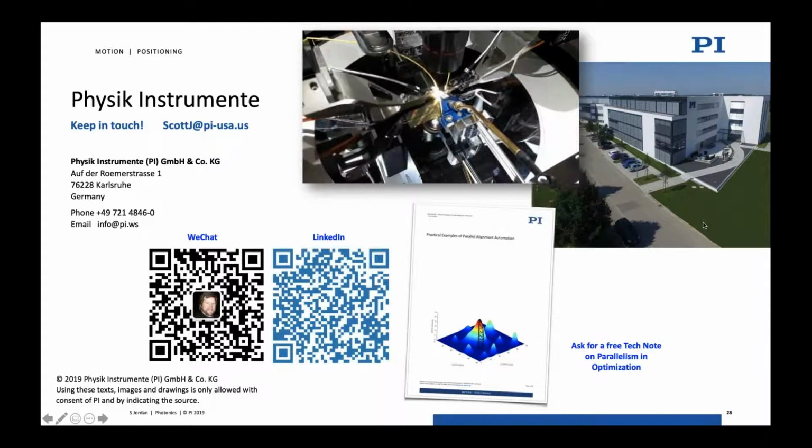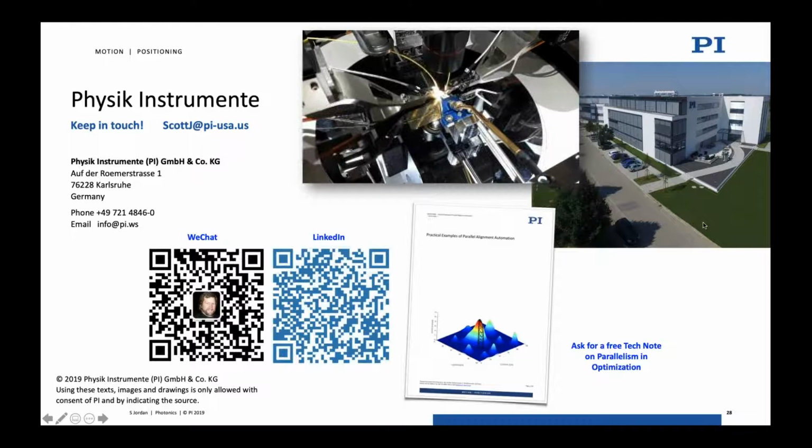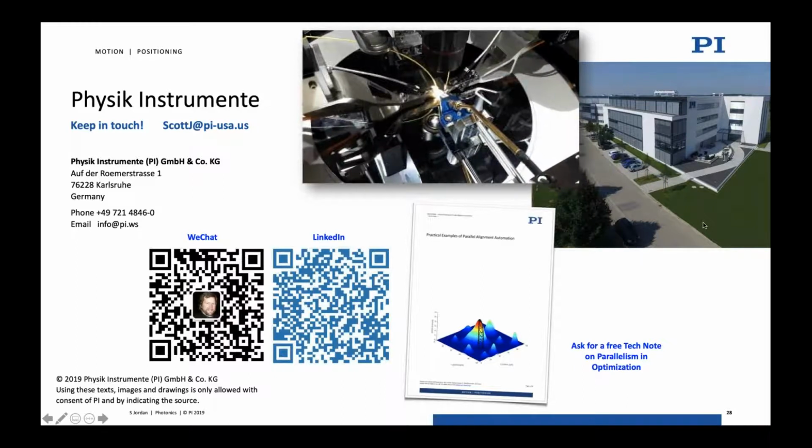And so it can compensate in real time for any misplacement of the rotational center point, which means we can perform the full 6 degree of freedom alignment in several independent processes. So there's an XY process, there is a theta Z process, there may be a gimbaling process, and there could be a Z process as well. If it's a lensed coupling, we can find the beam waist using a gradient search in Z. And these can all operate at the same time. Now, that's the key: this parallel actuation of this technology is something that was not possible before.